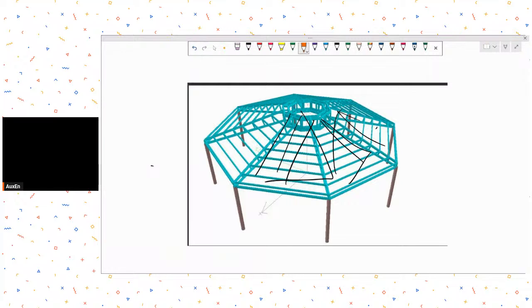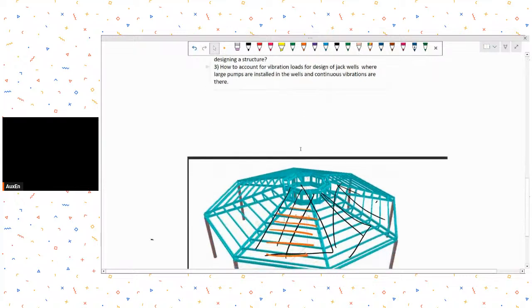And then of course you apply it on purlins if you want. If you want to apply it on purlins, you apply it as UDL: wind pressure multiplied by CPE multiplied by the purlin to purlin spacing. You can apply it as UDLs on these purlins. Okay.